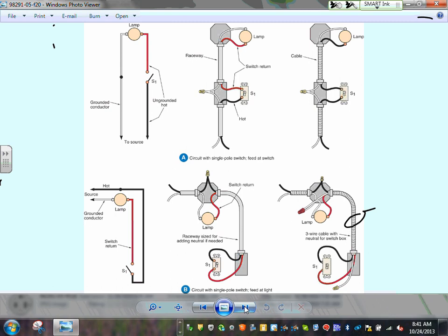But you need to be aware that this is how you bring the circuit. For example, you bring the circuit to a box, you bring the neutral to one slot, the hot comes in, tabbed, goes to the supply side, and returns into the lighting fixture. That's how a power system works in reality. Schematics, how is the schematic for it? It's right in here. That's the series parallel circuit that you did with Amy and what not. You can bring the circuit to the switch, like here, or you can bring the circuit to that light, like the one underneath it, with a conduit or a cable.